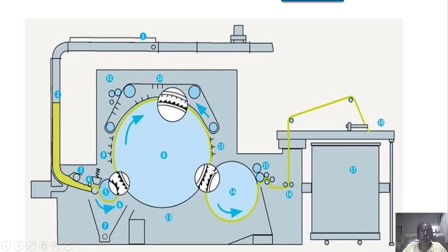And then the doffing arc, which is responsible for transfer of material from the cylinder to the doffer, is also shown in a magnified way here. So one can see the cylinder is rotating from back to the front. This Licker-in or Taker-in and doffer are moving exactly in the opposite direction.